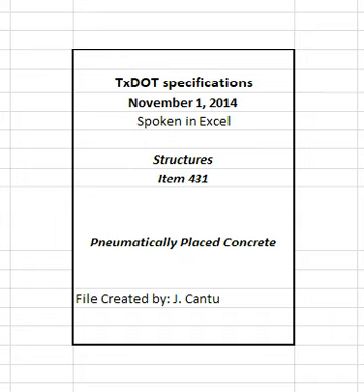Provide at least 1 inch's clearance between the finished concrete surface and all steel items including anchors, reinforcing bars, and wire fabric. Lap adjacent fabric sheets at least 6 inches and tie together securely at a spacing of no more than 18 inches. Pre-bend fabric before installing to fit around corners and into reentrant angles.